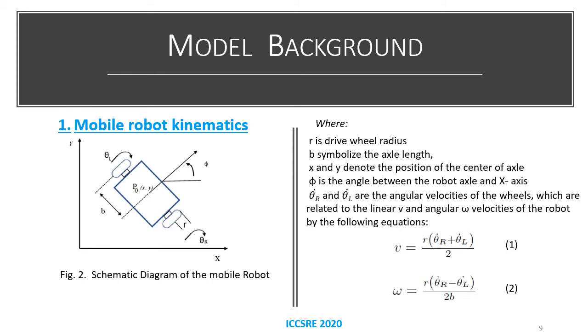Before an energy model is developed, it is extremely important to understand the kinematics of the differential drive robot system. A differential drive robot has two driving wheels which are attached to DC motors and a caster which is added for balancing. The rotation of the motors causes the wheels to rotate, producing linear and angular motions of the robot. A kinematic model is shown as follows in Figure 2. The linear and the rotational velocity of the robot are given by the following equations.